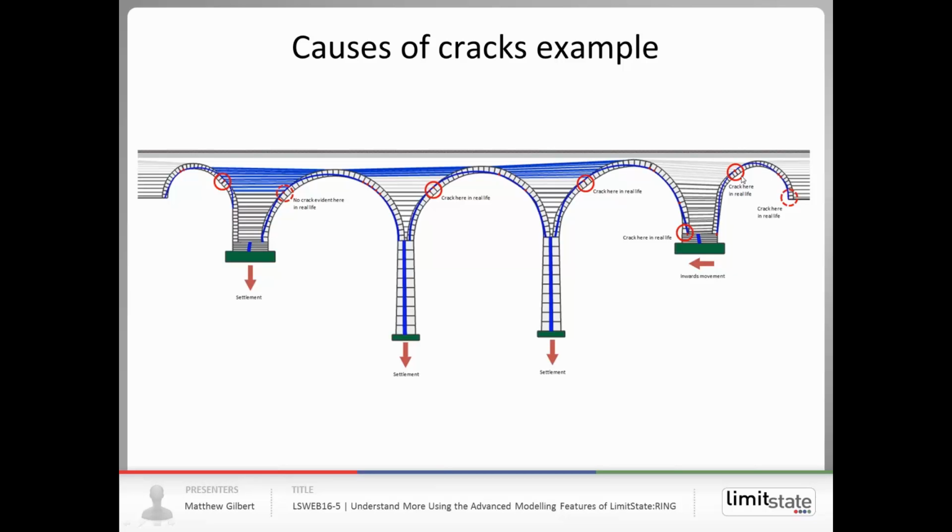Interesting thing is we found that the influence of the distortion on the load carrying capacity of this bridge was actually very small. So sometimes deformations can look quite worrying, but actually depending on the particular nature of the distortion that's occurred, they may not be that serious to the capacity of the structure.